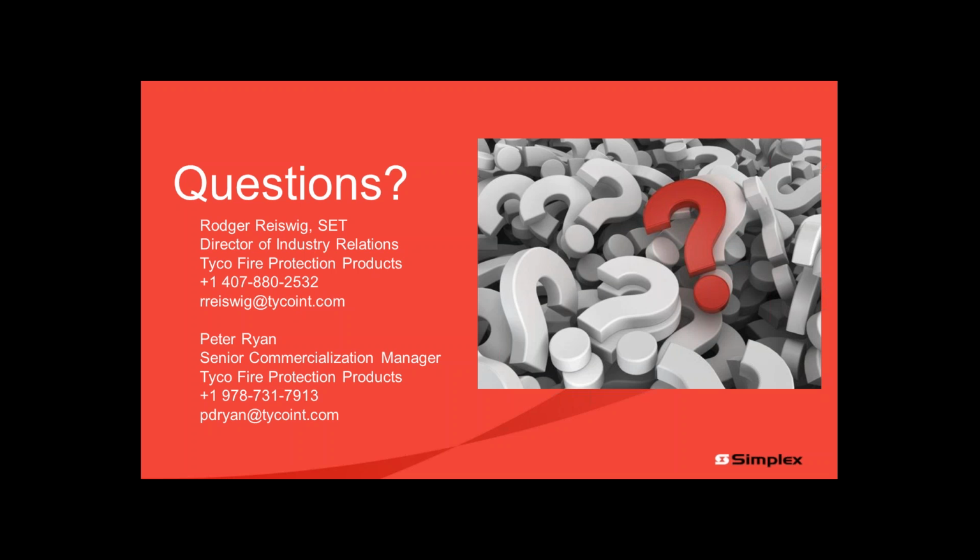So one of them is, can the fire alarm panel be integrated with cellular GSM modems, which can transmit messages and alarms on the cellular device? Yeah, great question. In our supervising station Chapter 26, we now allow, well, for several cycles now, allow GSM radio to be used to send signals off-site. And when we talk about cellular or mobile communications with GSM, there's really 2 ways about that. The one that's commonly used is, it's a crude way of saying it, but it gets the point across very easily.